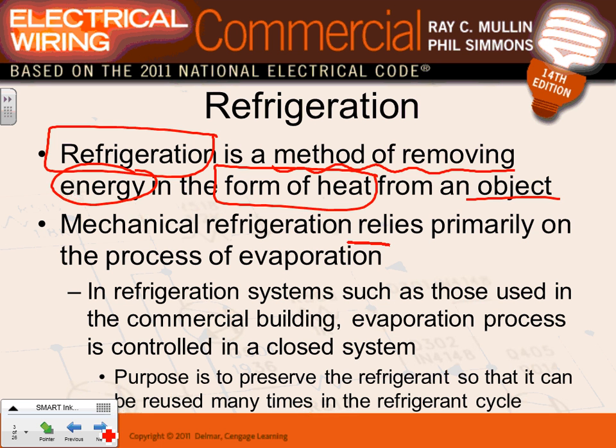Because of removing the heat, the evaporator, you guys remember that the evaporator inside the building is the single most important part of a cooling system, because that's what sits inside, and you take the air inside this room and blow it right through the evaporator coils. They're basically loops of pipes. You blow the air right through them.